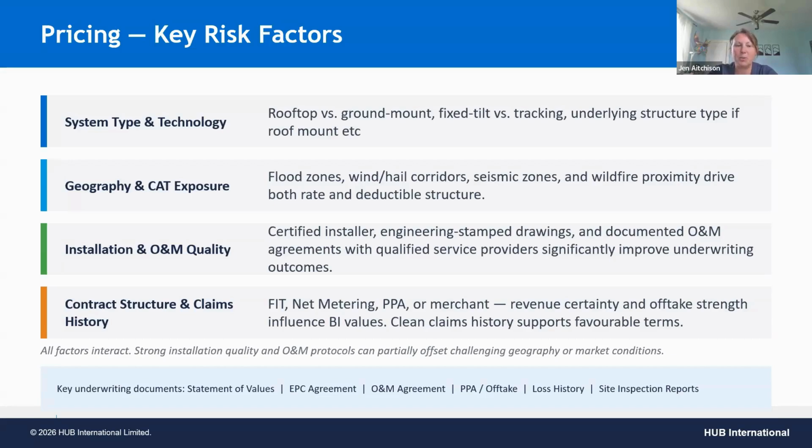So the insurers are paying close attention to natural catastrophe. They have certainly been burned by natural catastrophe and paid significant losses here. So they will pay close attention to where you're installing and what you're installing. And if you're doing a big build out and you've got some solar farms that are exposed to hail and you're expecting to operate, understanding if you're tracking in Alberta, making sure that your track and stow procedures work, even if only part of the farm is partially complete, is just good practice.